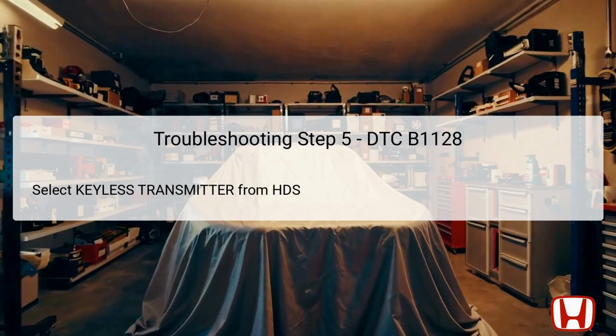With the driver's door lock switch in the neutral position, select the keyless transmitter from the HDS and enter the data list. This process allows access to real-time data flowing from the vehicle's modules, particularly focusing on inputs from the keyless entry system. The neutral position ensures that the switch isn't inadvertently sending any signals while testing.